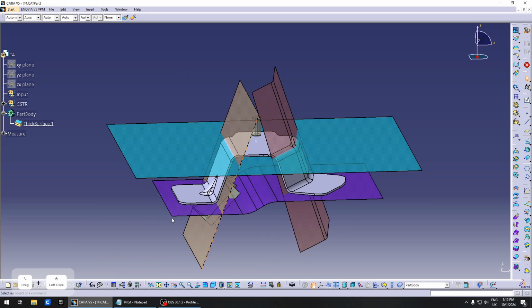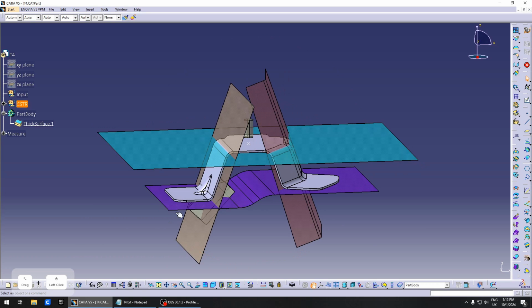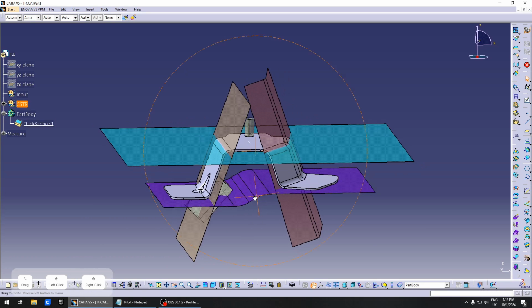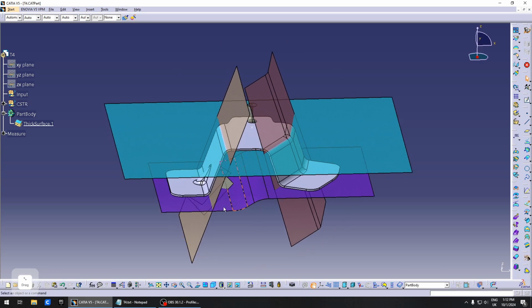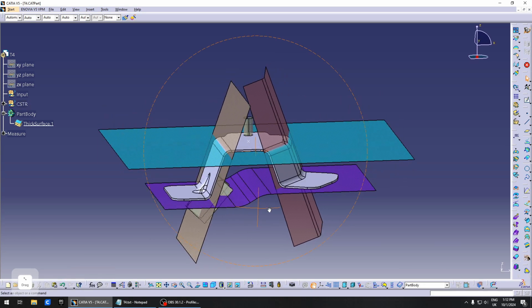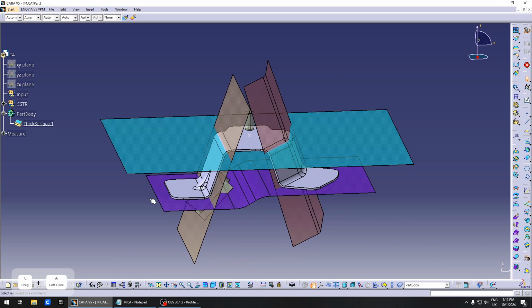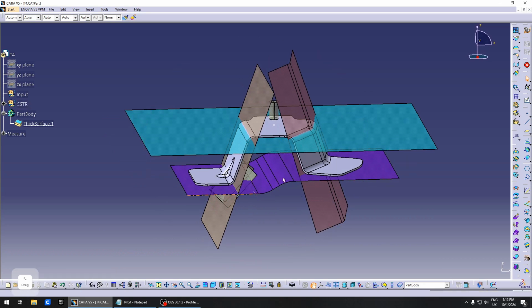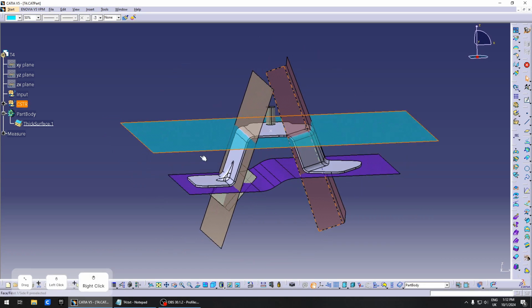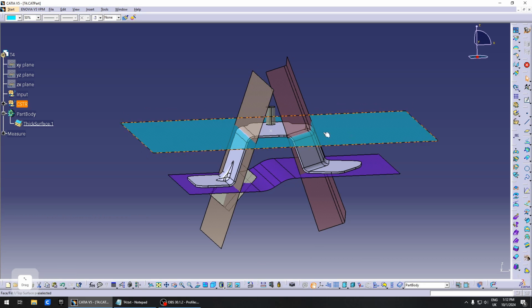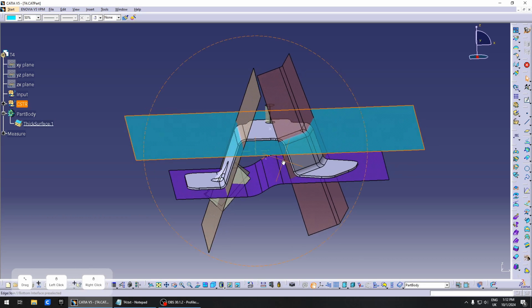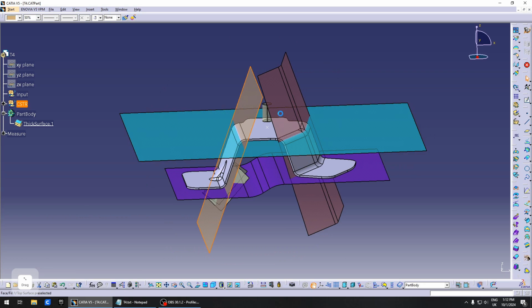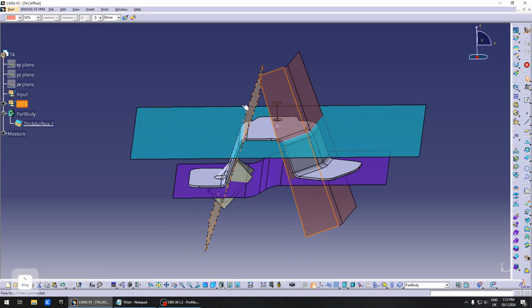You will have your base surface. This is generally a mating surface. This can be 1, 2, or even 10 surfaces, depending on how complex your part is, or it can be something totally different. But this is the basic idea. You will have something that is usually a functional surface, which is this one that you design yourself, you define yourself, and then you usually have some way to connect those two surfaces together, which are these two walls.